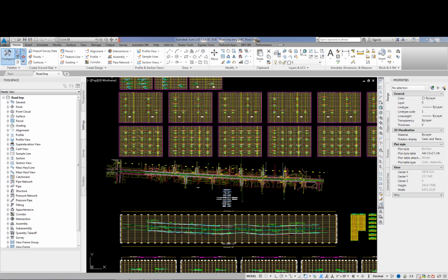The final step in the preparation of the road improvement drawing is to create the construction notes, hatch the improvements, and create data shortcuts of the road alignments and profiles. The concrete road improvements will be XREF'd into the other improvement drawings.